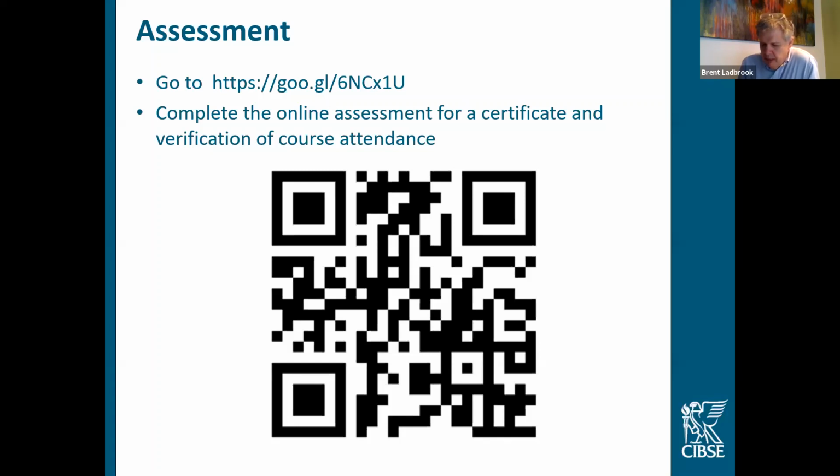So we also spoke before about dynamic ranges. Typically, by default, these are 100 to 1. And in instances like this might be an example where you have a dynamic range or a turn down ratio of 250 to 1, so you can capture much lower flows. So they're a little bit more expensive because there's more calibration that goes into them. But where you have high ranges and you want to capture them both accurately, then this wider turn down ratio might be well worth investing the money in. And until I saw the exact flow rates, it's hard to comment further.